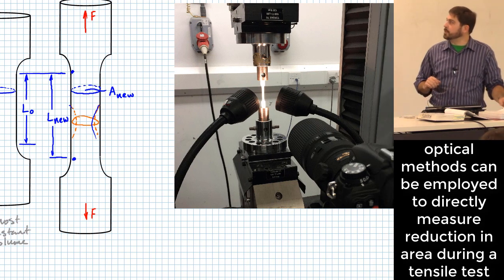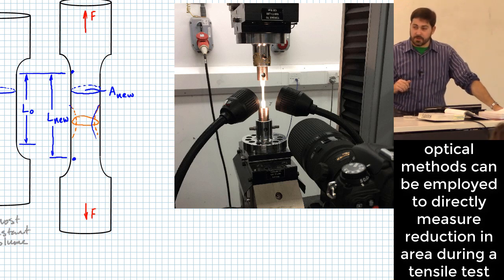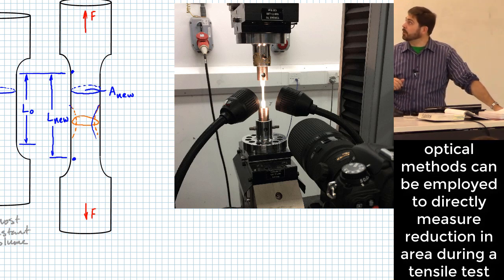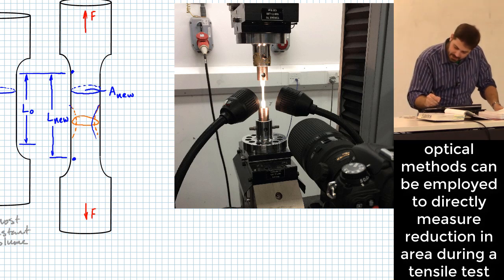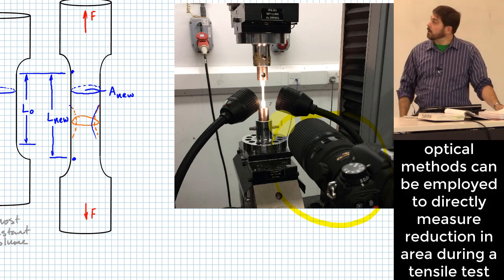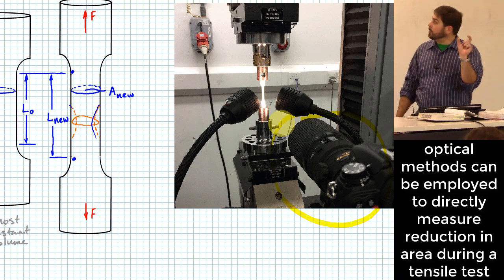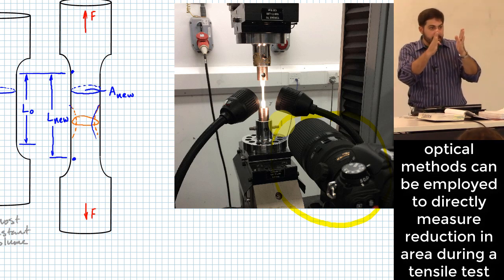What do you think they're doing in that picture? What they're doing, those two things you see pointing at that specimen, are lights. You're trying to get plenty of light on the specimen. What's this thing down here? That's a camera. So what are they trying to do? They're probably trying to measure that specimen with that camera and get those values as best they can. And one of the things they are going to be able to find with that is cross-sectional area as it begins to deform.